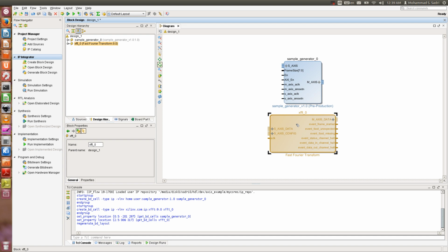So the FFT implementation does not need to accept a new sample every clock cycle. It needs to accept a new sample every 4 clock cycles, so the logic can be reused during these clock cycles. It can instantiate a single piece of logic and reuse it through these clock cycles. The result is a smaller circuit for the FFT module, and this is what designers usually do.